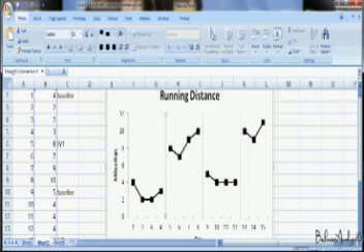So I'm going to right click here, somewhere in the graph. Right click on the drop down menu, select Paste, and it actually pasted it right on top of the other one that I just copied. So I'm going to left click and move it over to the phase change where I want it to be, and release.